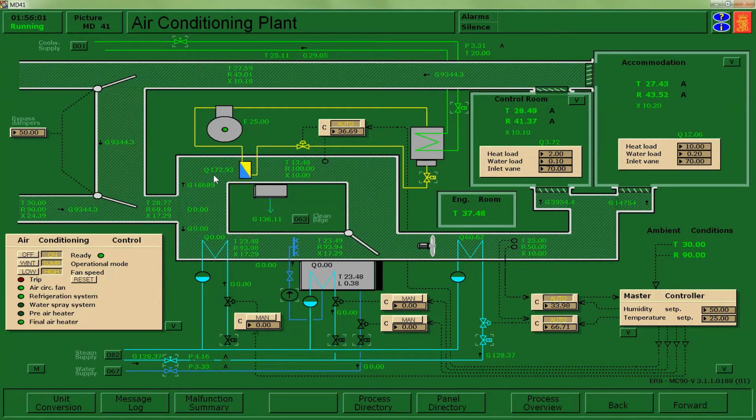Sometimes, though, if we do it too much, we are going to recycle stale air, lack of oxygen. So we may be hesitant to commit 100% to our bypass. So always we want to have some fresh air in. The more fresh air you have in general, the more energy it's going to cost you to condition your space. Okay, I'm going to just send it back to 0.